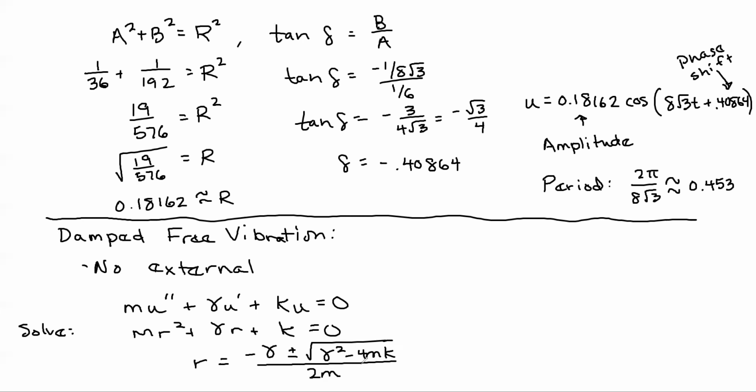If m, gamma, and k could be any positive values, you could have any mass, any damping constant, and any spring constant, any positive values in these three spots, we could get a range of possible solutions to the quadratic formula. We could get all of the solutions that we've discussed in previous videos. We could get 2 real solutions, we could get 1 repeated solution, and we could get complex conjugates. So there's 3 possibilities, and this case has all these possibilities that we've got to look at.